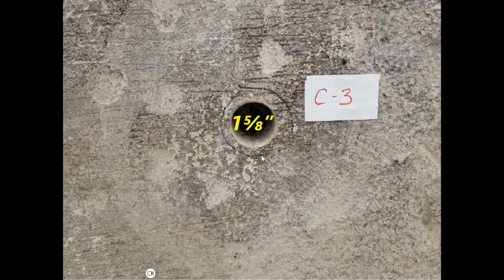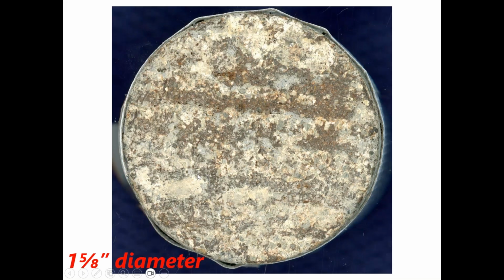We took a core into the wall of the pool, and there's a close-up of it. You can see that each of these reddish colored lines used to be a strand of steel. Okay, look, it's not that anymore. It's clearly oxidized and kind of corroded away.